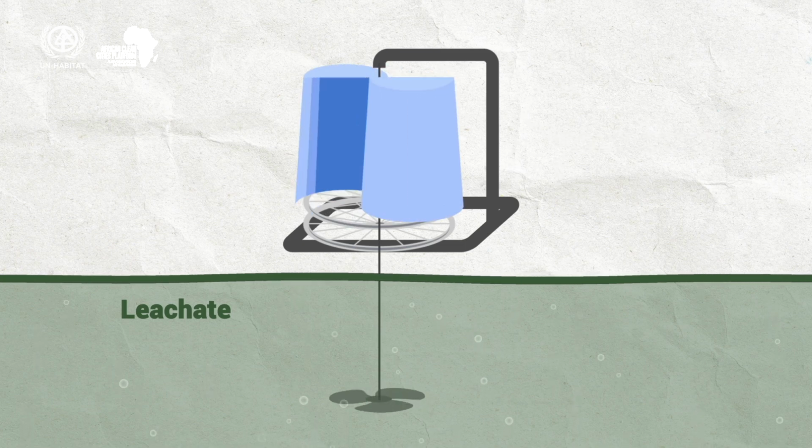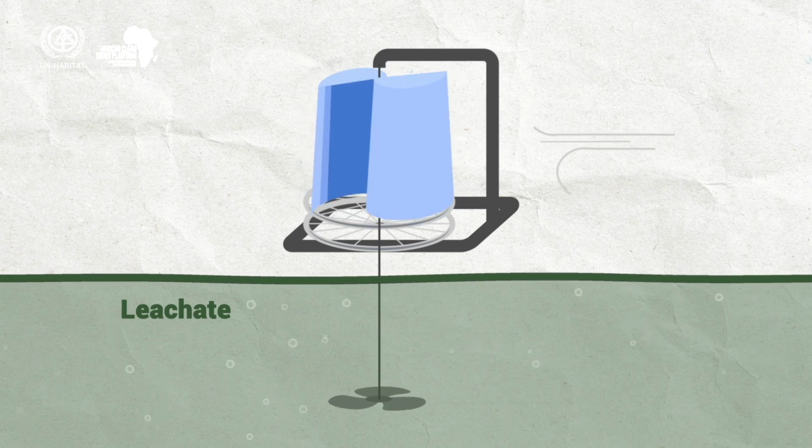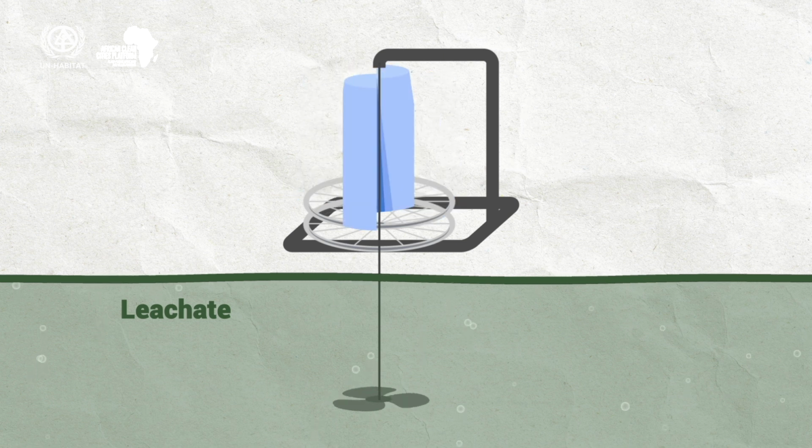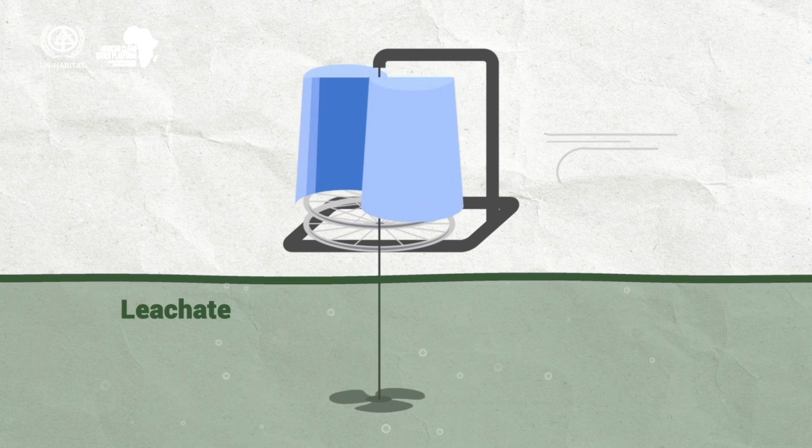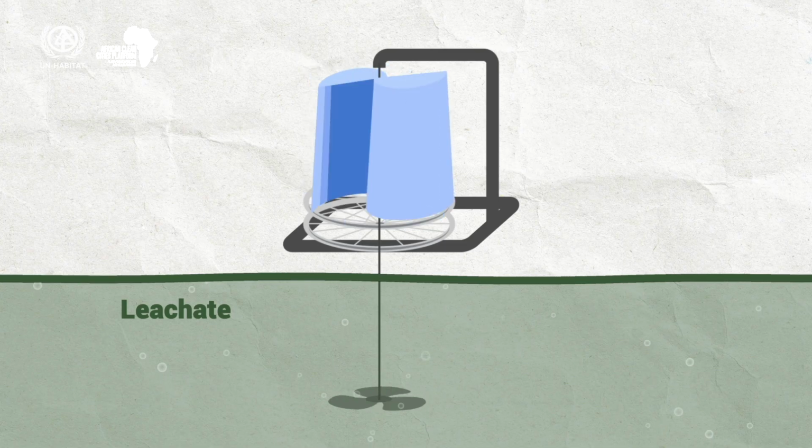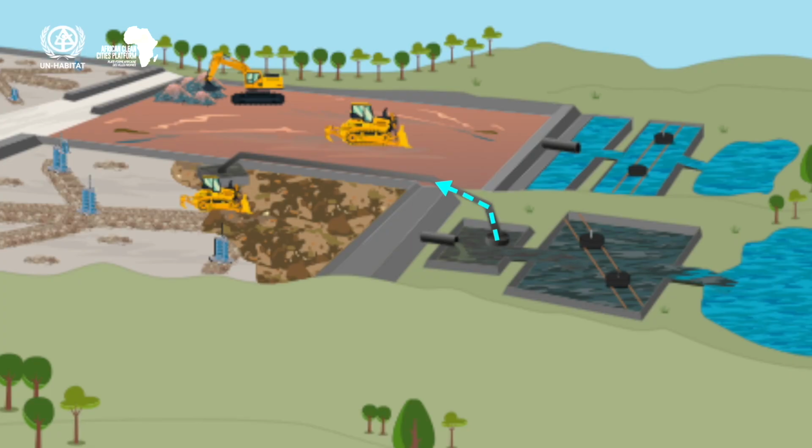But it's only suitable for dealing with wastewater pollution caused by organic matters. It cannot deal with non-organic waste such as heavy metals. Where these are present, it's possible to use a landfill as a filter by passing the leachate back through the site. This keeps the toxic waste elements in the landfill as much as possible. However, leachate recirculation is only possible by pumping back the leachate from a leachate treatment pond at lower ground to the top surface of a landfill structure.